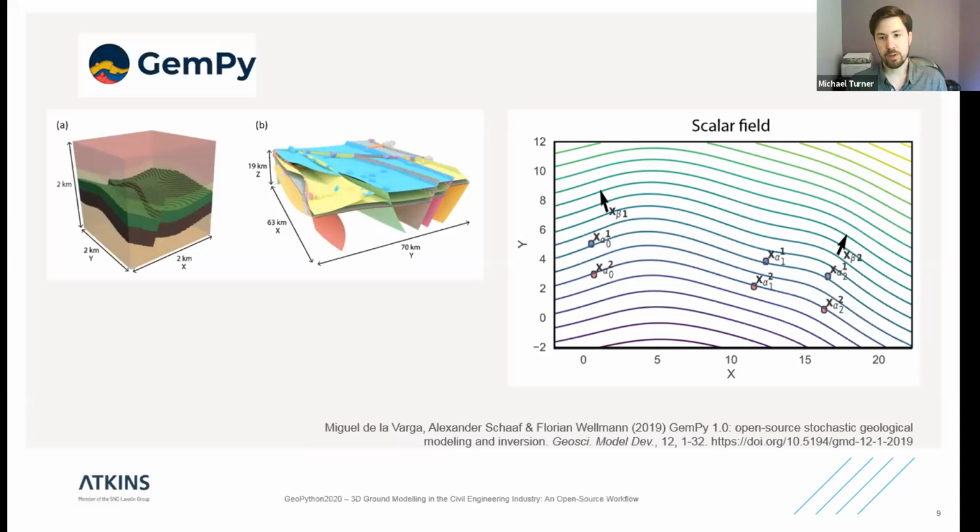Now, this technique was developed for modeling quite large-scale features in hard rock proper geology, if you like. And that's quite different from what we're normally worried about for civil engineering projects, which are often dominated by near-surface, highly variable deposits. And this could cause some challenges. For example, it's not immediately clear that the interpolation function used to calculate the scalar field would necessarily be applicable to the superficial materials, but we thought it'd be interesting to give it a go and see.